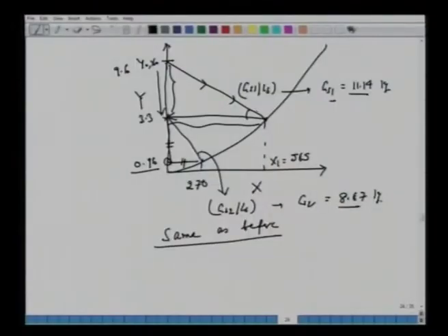Well, we start from here. This was stage 1, then you have stage 2. So if the solvent is given, the amount of solid is given to us, the solution is given to us, then the slope we can find out. There's no iteration required. We can come to this equilibrium curve and calculate these intermediate numbers. Then we know the second slope, GS2 over LS.